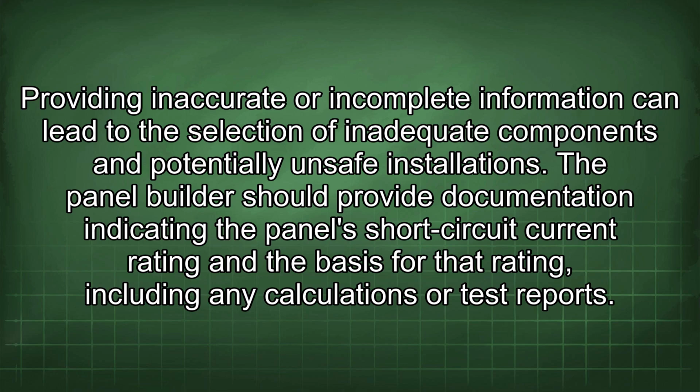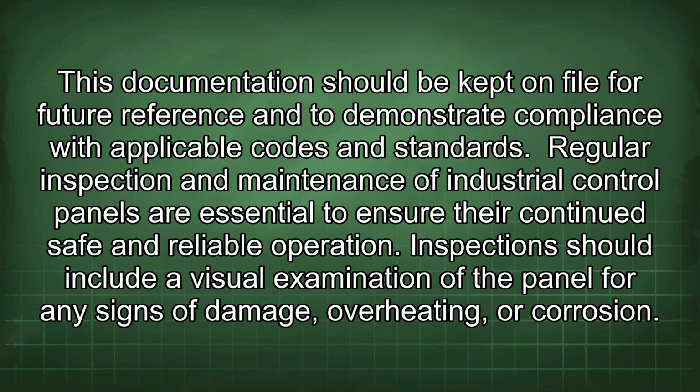The panel builder should provide documentation indicating the panel short-circuit current rating and the basis for that rating, including any calculations or test reports. This documentation should be kept on file for future reference and to demonstrate compliance with applicable codes and standards.